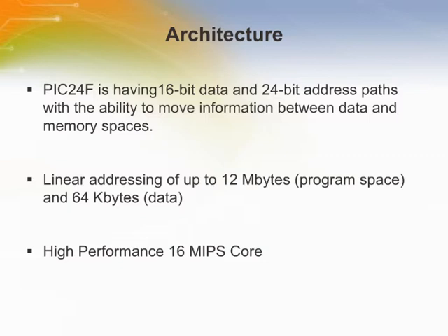PIC24F is a Harvard architecture which has separate data memory from program memory. Speed of the processor is 16 MIPS. When operating off a 32 MHz clock, the PIC24F can expect the performance to be roughly half of the clock rate, or equivalent to instruction execution time. In addition to faster execution time and 16-bit data bus, there are several other additions to the core.